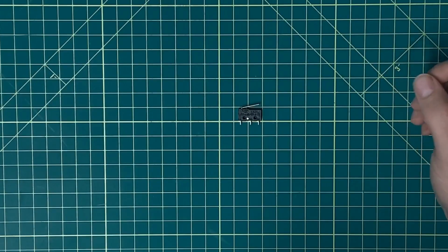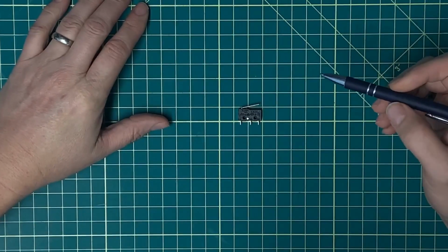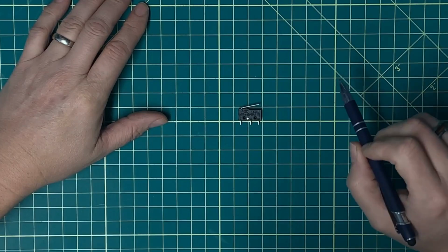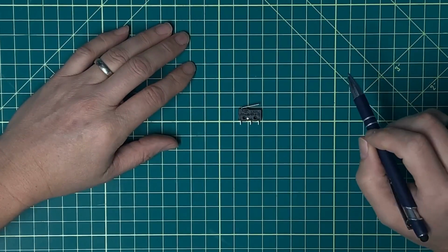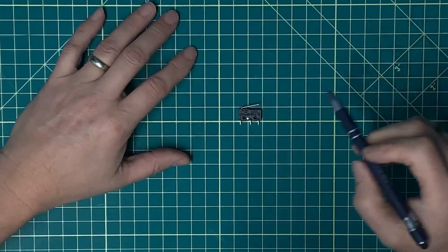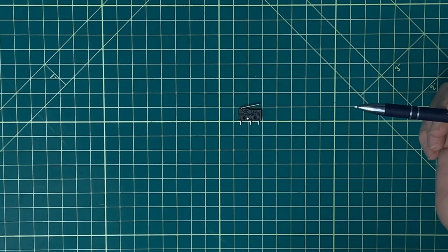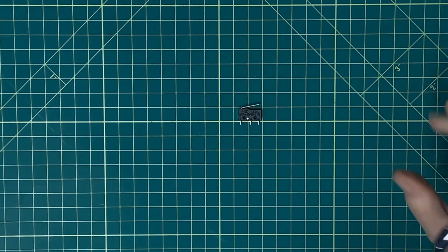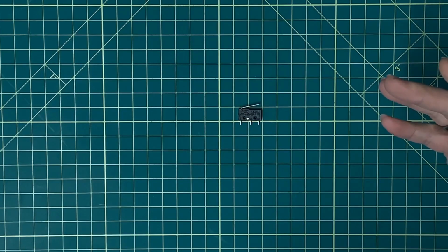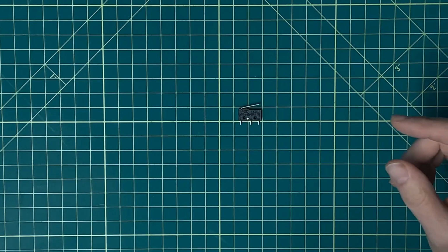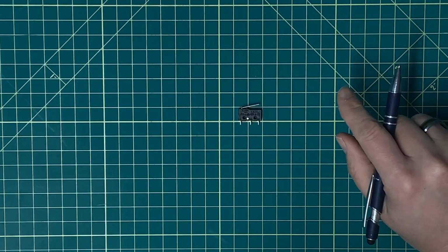The final thing I want to work on today is this switch. I need to change my timer, and in order to do that I actually need to change the type of switch that I use for my single step. What I've got is a single pole, single throw momentary push button, which means that normally the contacts are open, not conducting electricity. I push it, it releases. When I release, it goes back to its normally open position, but while I've got it pushed, it's closed.